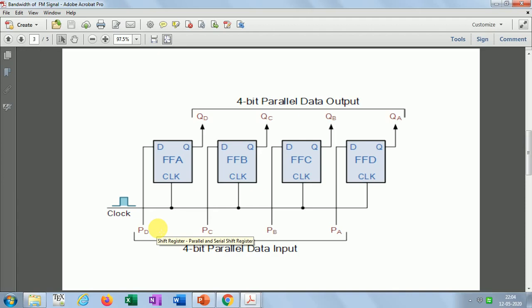In a similar way, you can consider a counter as a special type of register. If you remember the counter, it is also a combination of flip-flops that goes through a predefined sequence of states, right? So in that way you can also treat a counter as a register, because it is a collection of flip-flops, but they flip through different states that are predefined by the designer.